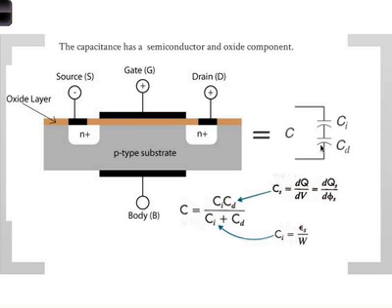Now, CD, the depletion capacitance, is voltage dependent. Very similar to the PN junction that we talked about before. So you have to do a differential. So CS, CD, which can also be thought of as with an S because it's a semiconductor, is dQ over dV. And the surface charge density is typically what's taken.